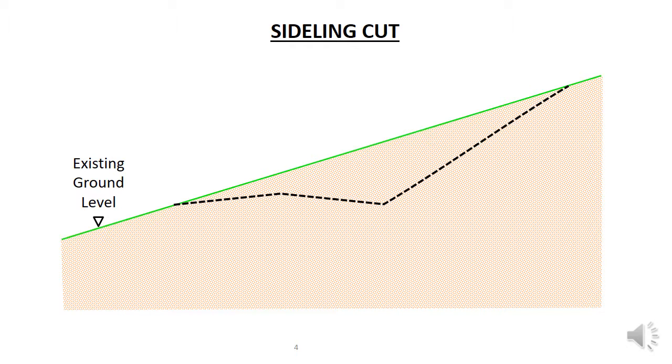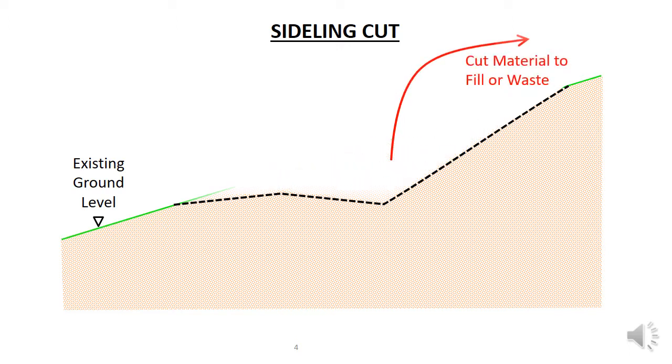In this case, one side of the road can be drained by letting the water flow off the low side of the road, although care needs to be taken to ensure the runoff does not erode the slope under the road. If that is a risk, then it is best to put a drain in beside the road and transport the water to a safe disposable area. There needs to be a drain on the other side.